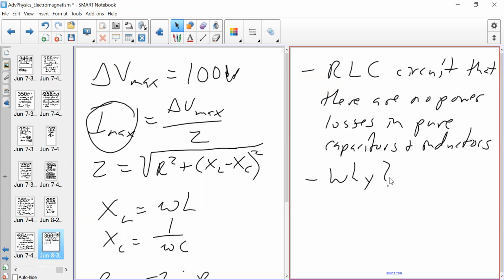nature of this circuit. So the AC voltage source is going to be cycling through the circuit at, say, 60 hertz or whatever the frequency is, and then for every circuit component, namely the inductor and the capacitor, it's going to go through, like for the capacitor, 2 charges and 2 discharges in one whole cycle. So when you take both of those, let's say the positive amplitude waves, and add them to the negative amplitude waves, you're going to get a net zero power loss. And the energy in those waves are basically going to cancel each other out for each half cycle.